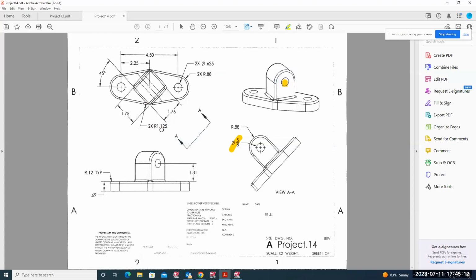So create that radius, which is, like I said, 1.275, not 1.125. Make a note on that. So I'm going to go to arc polar in the top plane, draw these two arcs and draw these two circles, which is radius 0.88. And then we're going to create these two arc polar, and we're going to join this with the tangent line.